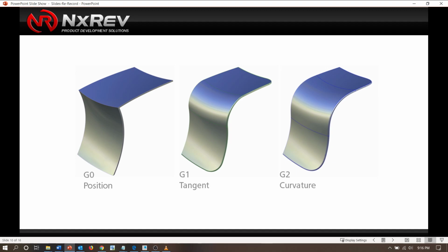And even though it's smooth, there is a characteristic break line that you can see, right? A shadow of where the transition from the flat surface to the round is located. And then all the way on the right, which is what we're usually after, is curvature continuity. So it's a little trickier to describe, but technically it occurs when the rate of curvature between two continuous surfaces are the same. And what that means for us is that visually, it is when you begin to not be able to tell when one surface ends and another begins.